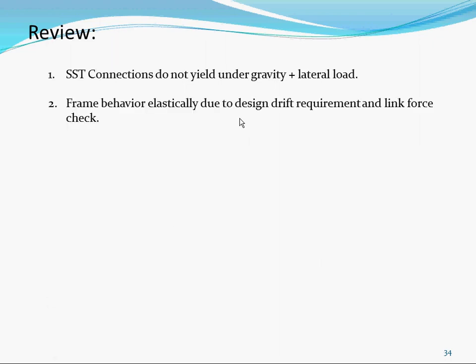Okay, so review. SST connections do not yield under gravity and lateral loads, and that's what we're trying to do. The frame behaves elastically. Include the wind load. Typically when we say lateral, it's either wind or seismic. When you look at a load combination, I'll go over that later, you don't combine wind and seismic. You only do one or the other.